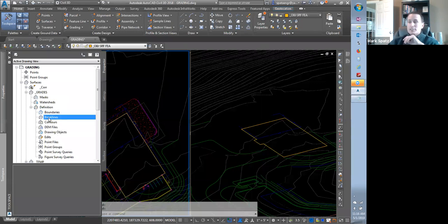I've seen other ways where people get hundreds of break line sets. And then the problem is you have no idea which break line set goes with which feature lines. You could try the process of elimination, going down through and doing select to see which ones it selects, and the workflow is horrible. What you need to do is just have one break line set.